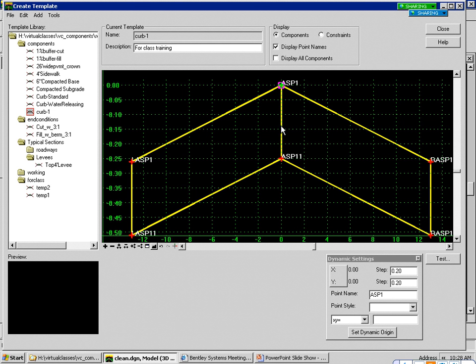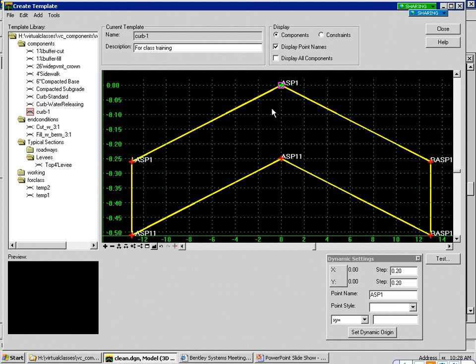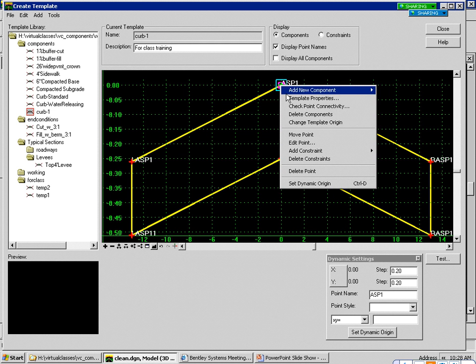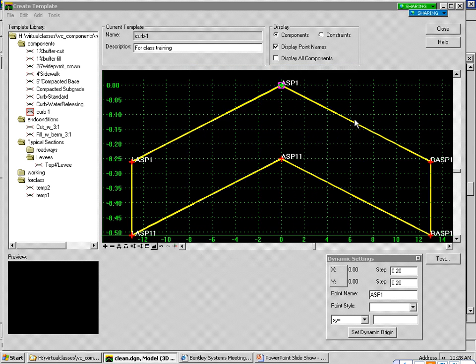Now, when I hover over things, if I right-click, because I'm sitting on the line, it recognizes we could probably merge this. So I can say merge, and that just now became one component. And that just resolved my duplicity on my naming. So now if I hit edit point, I've got one point there, and it's not constrained right there, and you can see we have one element.